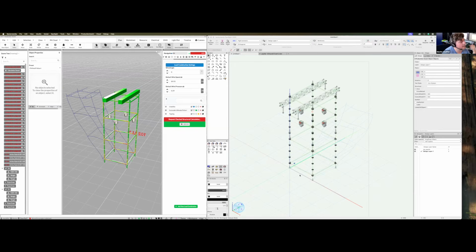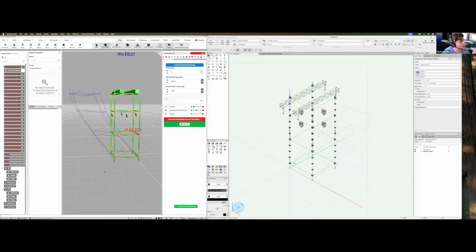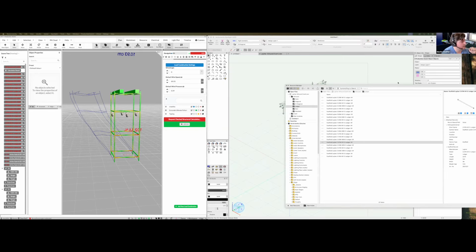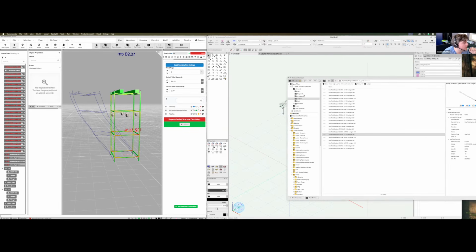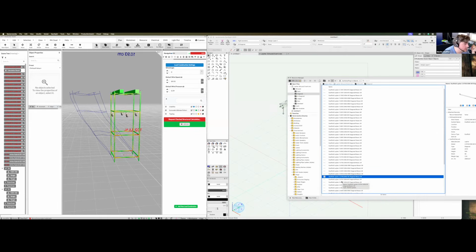The easiest way to fix this is to enter diagonals. The diagonals come from the resource manager, and in here I am selecting them. So what we need is the diagonals, and there are several of them, so we need the right ones. We need the 207s, and we don't need the 0.5 meter, but we need the 2 meter. Where do we have them? In here, 207 by 2 meters.